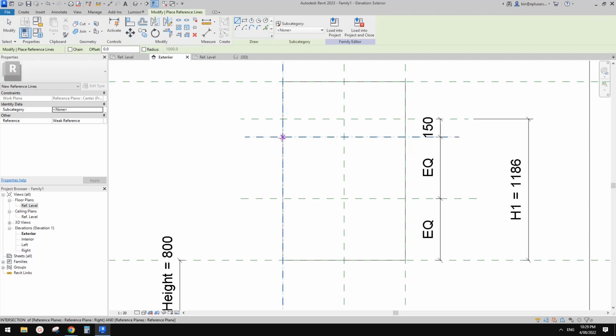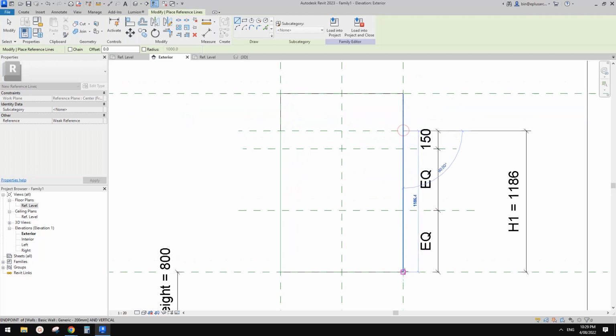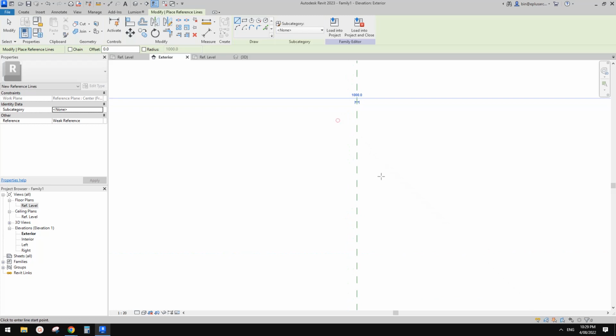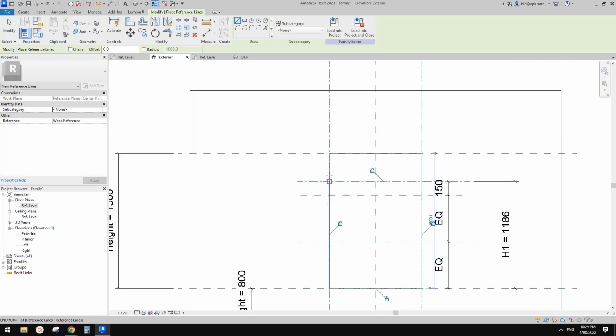Yep, all good. So I'll draw a line from, I think it's this one, H1, where the vertical meets the curve. I'll draw one, and straight away you can lock it onto the reference plane. Same for another one here, lock, and another one, lock here. Oh, they're stacked together. Okay, so another one here, and lock. Now we need a curve.